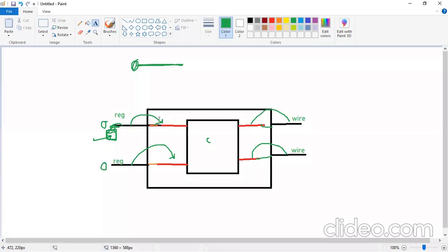So see here, in design you have taken input, right? This signal is your input signal, right? In design, yes, this signal is also an input signal. This is your output signal in design. So by default, all inputs and outputs are wire data type. Suppose you are writing input and output, so by default it is wire data type. So this is wire type.